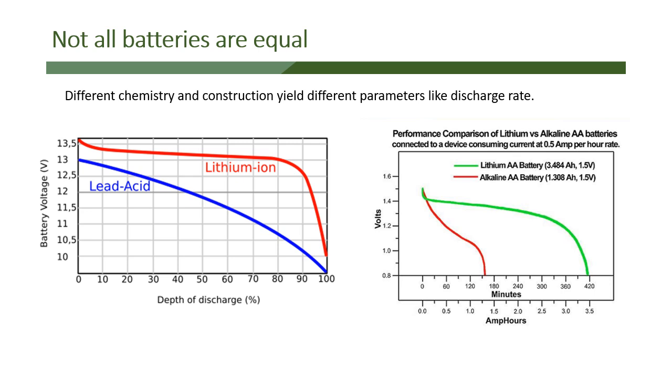As you can see with the red line, the lithium ion batteries try to maintain their voltage as long as they can until they reach a point where they can no longer maintain that load, and then they begin to discharge and deplete much faster. So the lithium ion batteries can operate at a fixed voltage level for a longer period of time than lead acid. The other thing that lithium ion can do is it can be recharged many, many more times than lead acid, and they're also lighter.